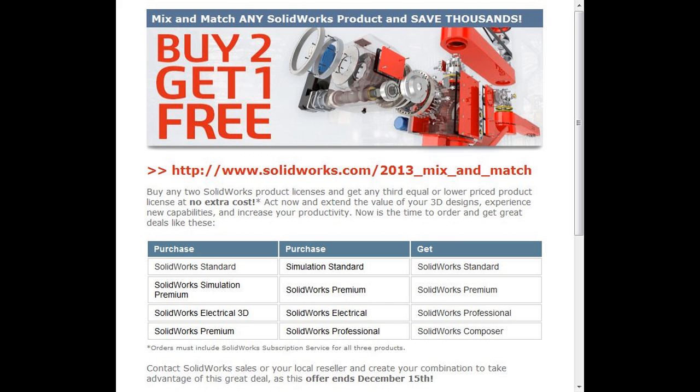You can toy around with those. Change your fillet order in the tree just by dragging one fillet before another and testing it. That's a great way to do that. There's no general rule of thumb. There's no precise right way. Like I said, I like to do big fillets before little fillets, and I like to draft early.